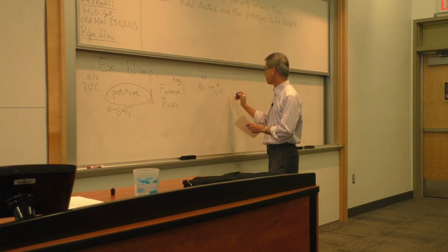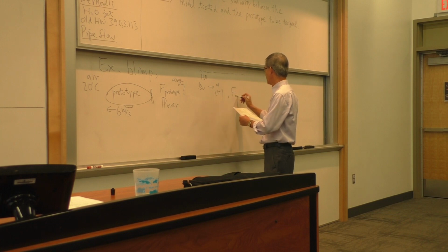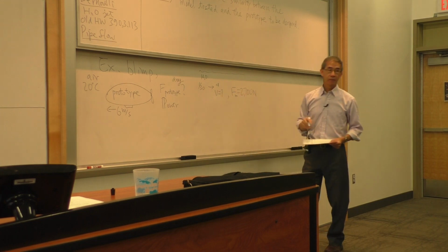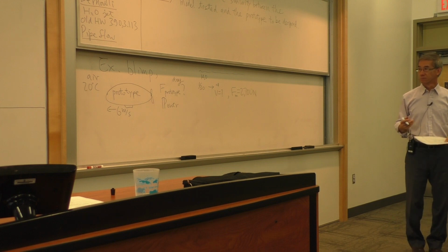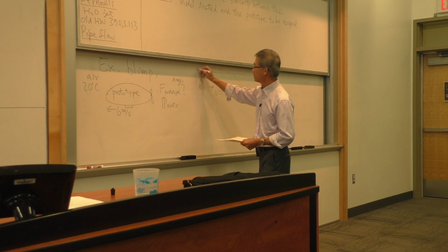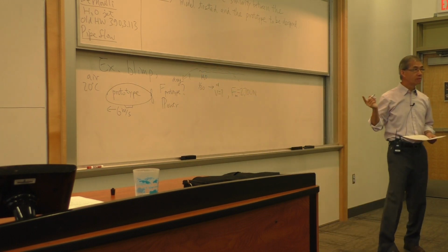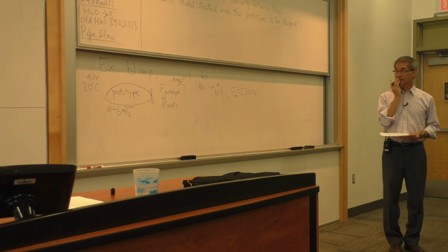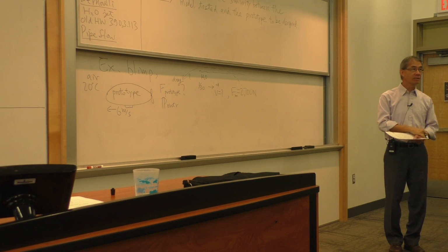And after that, if at this speed, I measure my model drag force, at this speed that is to be determined, I measure the drag force to be 2,700 Newtons. How do I take that experimental data and hope to infer, for this 30 times bigger airship at 6 meters per second in air, not in water, in air, what would that force be? What would that drag force be?